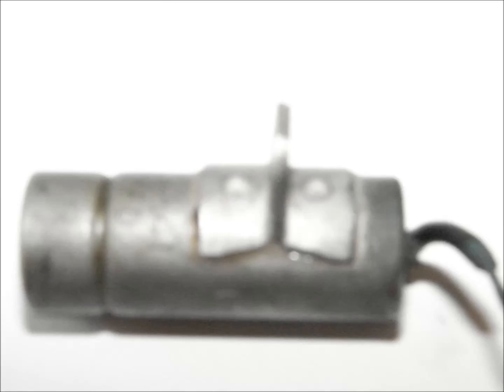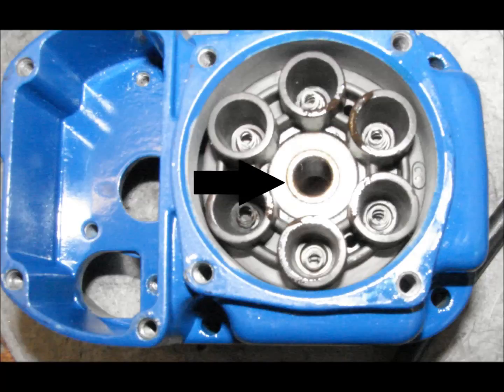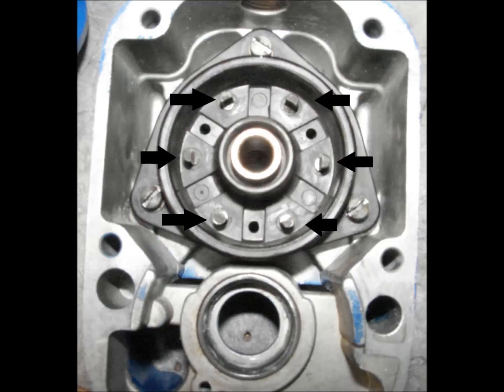The capacitor's only job is to prevent the current from the primary winding from jumping across the breaker points to ground. The distributor block is the connection between the magneto and the leads. The distributor block has a center boss in which the distributor shaft rides. The distributor block also has electrical contacts. High-tension